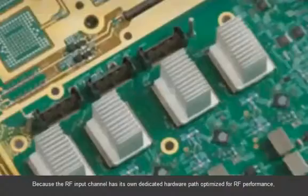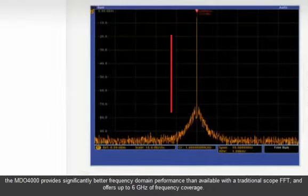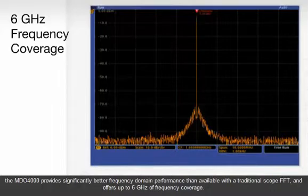Because the RF input channel has its own dedicated hardware path optimized for RF performance, the MDO4000 provides significantly better frequency domain performance than available with a traditional scope FFT and offers up to 6 GHz of frequency coverage.